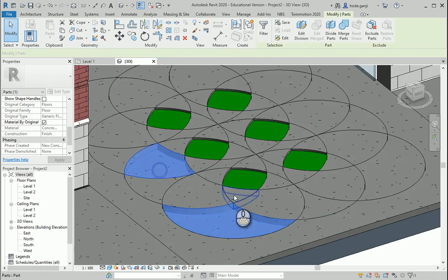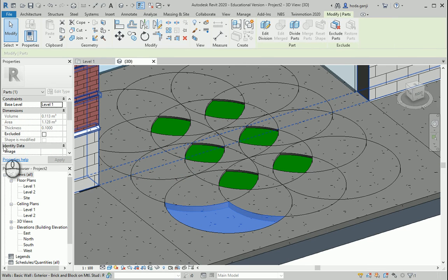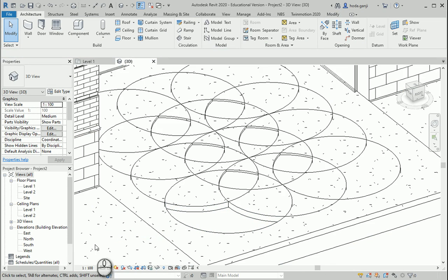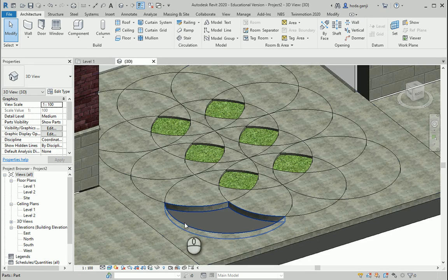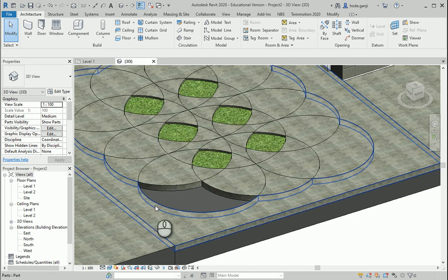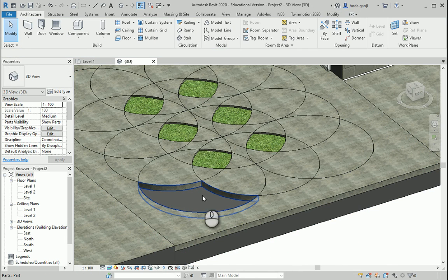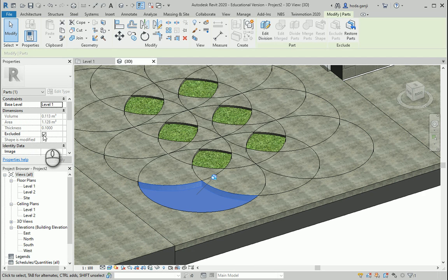You can, for instance, work on these parts. There is also an option named excluded. If you check the box for excluded, it's not going to show that specific part at all. So it's going to show the layer below that, which is the structure, but that layer is just missing over there. Okay, so I want to remove the check mark. I don't want to exclude this one.